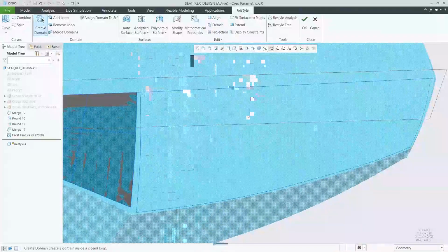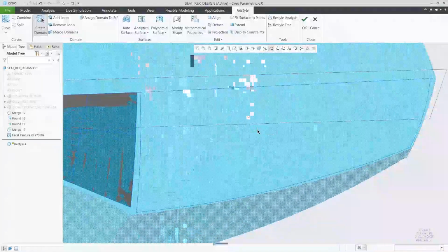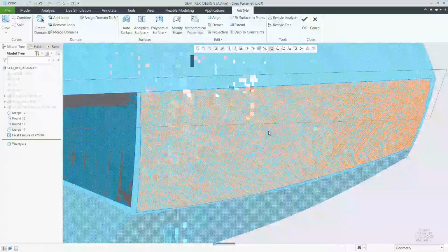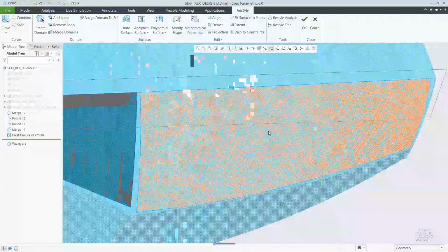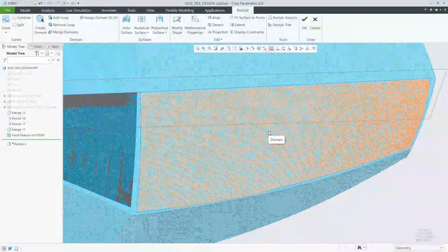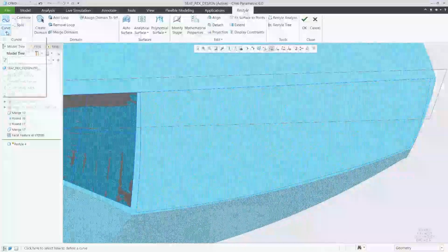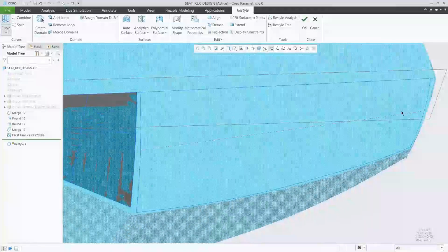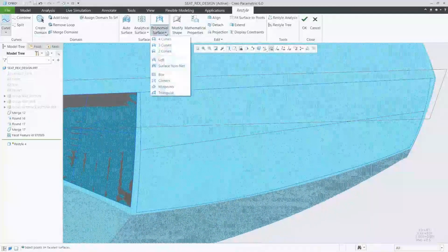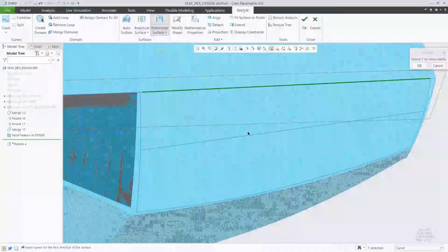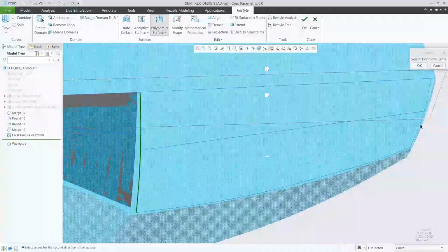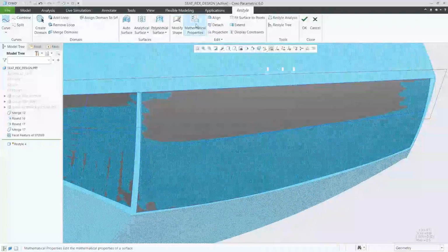Right, and once we have that outer loop defined, we can go ahead and specify the domain of points there in the middle again. So again, those are just going to be all the points that are bound by those different curves that we laid out, and allows us to build out surfaces based upon that, do diagnostics on that domain of points that we want to create the surface based on. And we could analyze that further. But before we do that, let's go ahead and add in another controlling curve going through the middle of that area. And then we'll just go right up into our different polynomial surface options, which we have a lot of, depending on the use case that you're working around. Let's go ahead and build the surface based off of that.